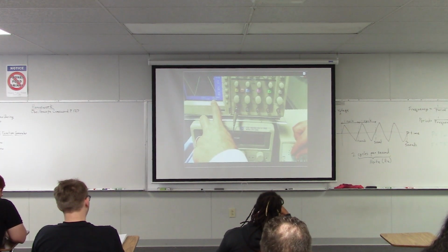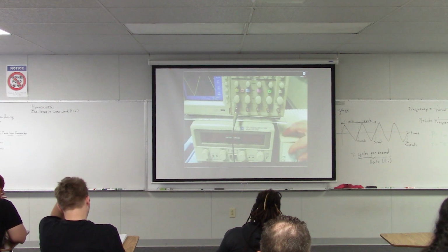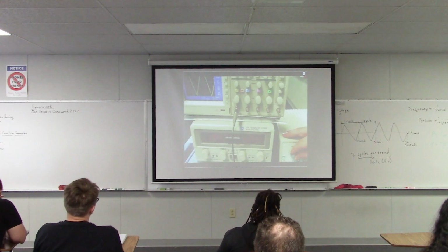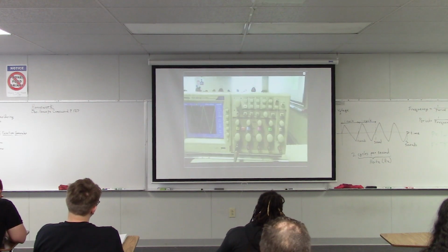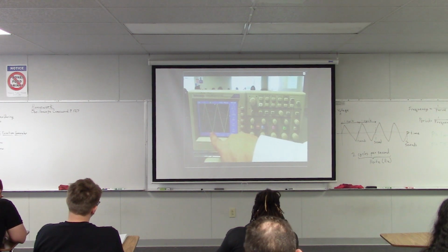Yeah. Could you also go over how you calculated it too? How I calculated the frequency? Mm-hmm. Okay, yeah. So this was up around 1,000 hertz. So then what I did was, what I actually measured was the period of the signal. So the way that I measured the period is I counted how many divisions there were in one cycle.